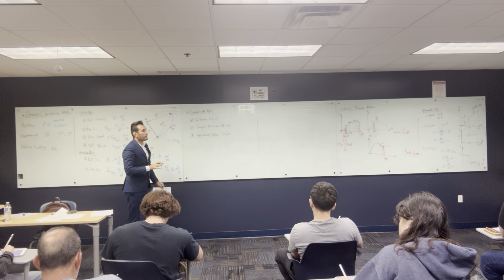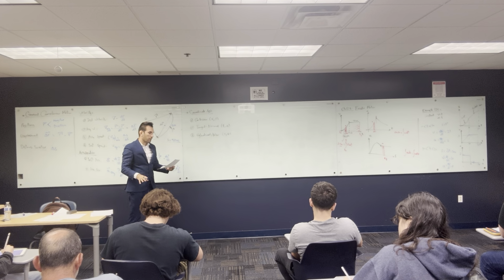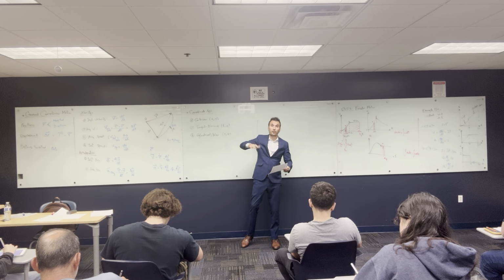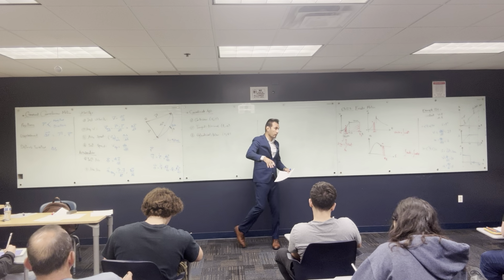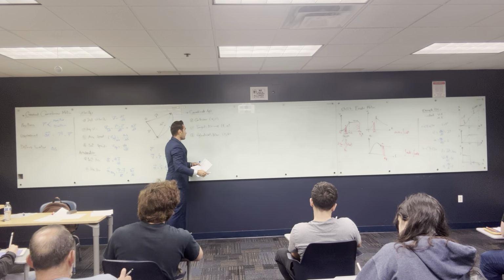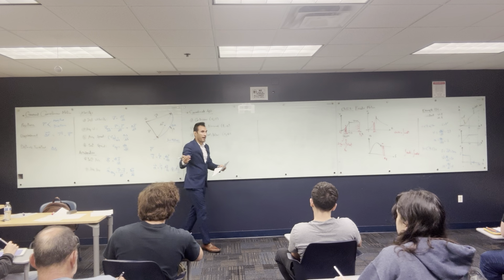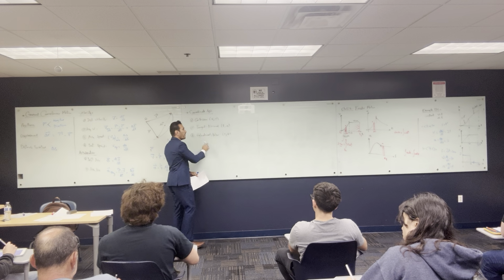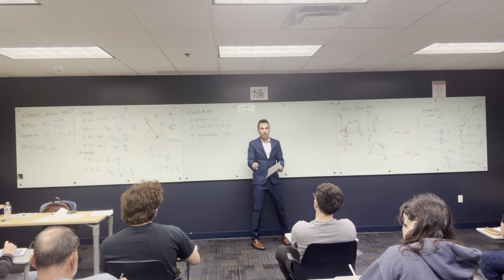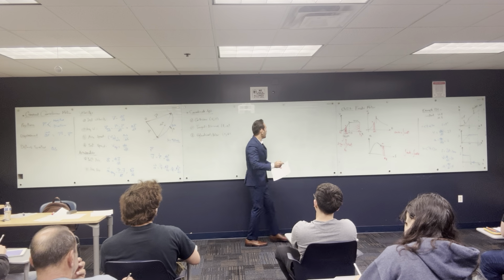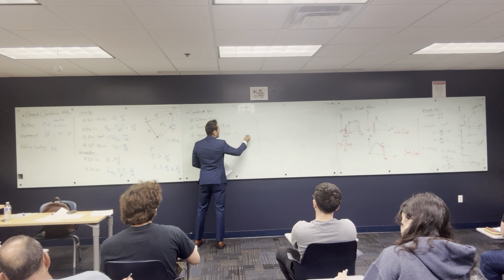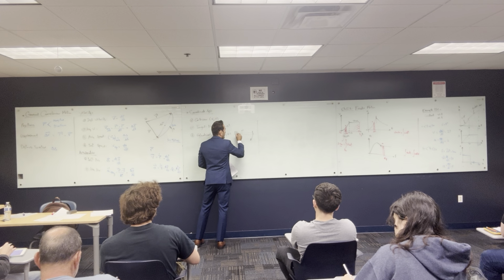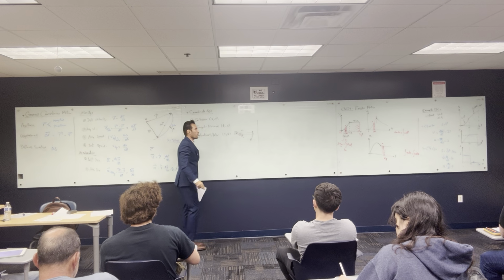We use each one of these depending on the type of problem that we have. If you have a gravitational acceleration, like a body moving under gravity, we know gravity is in the y direction, so usually we use Cartesian. If you have a body moving along a path, a curve that I gave you already, we use tangent normal. If you have an arm in a mechanical system, hinged here, and this arm is moving with an r and theta, we usually use the r theta coordinate system.